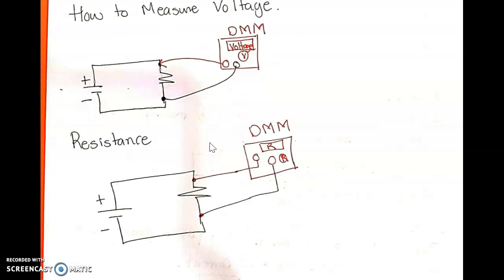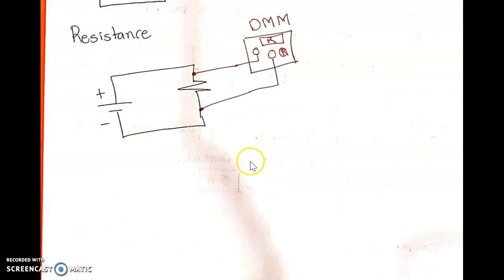The same way we measure resistance, it's just across. We don't have to do anything to the circuit. We just change the setting to read resistors now, or resistance, and we leave the same connections. We don't move the leads either. We can use the same lead connections.